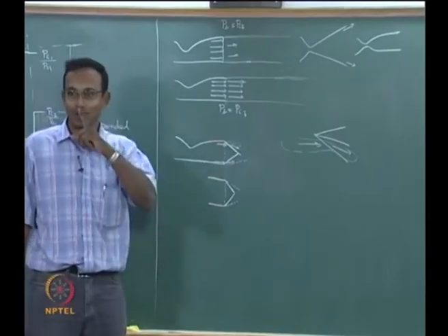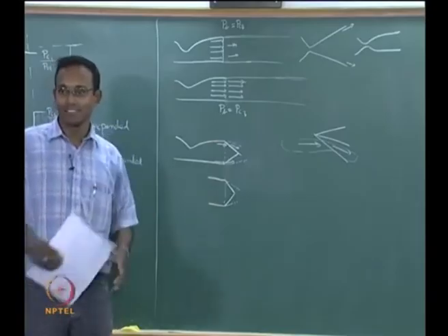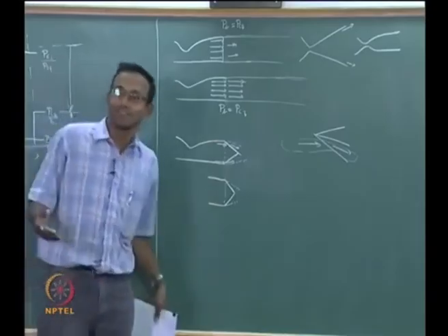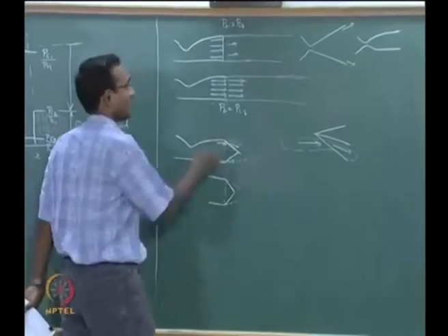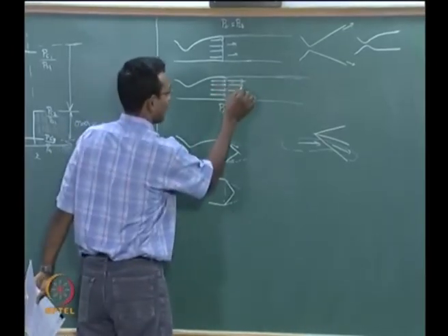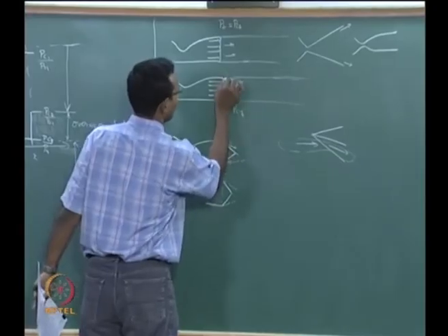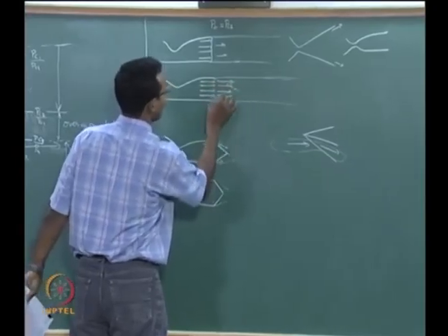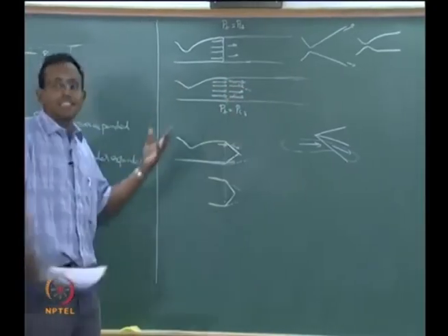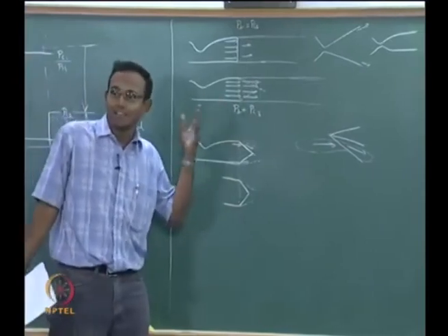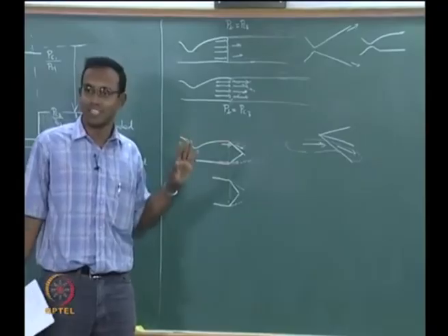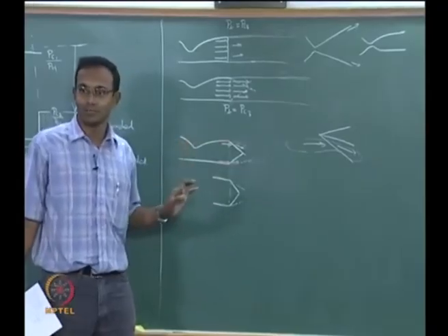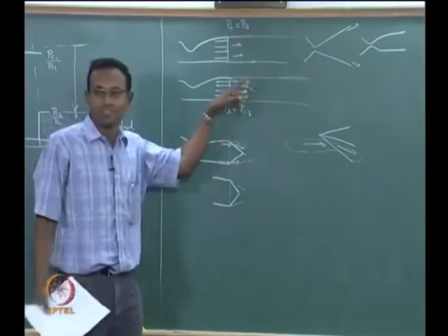Beta will go to mu, the Mach angle, that is the weakest shock you can ever have, right. Beta will become mu, that is a specific reason why I asked this question. In fact, if I draw that particular beta here, it will just become that Mach wave, which will just tell the fluid not to change anything, right. We always talked about Mach wave as a wave that says stay as is, do not increase pressure or decrease pressure. It is a wave that says do not change anything.